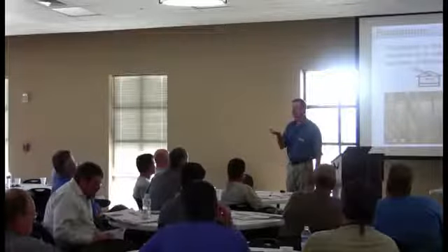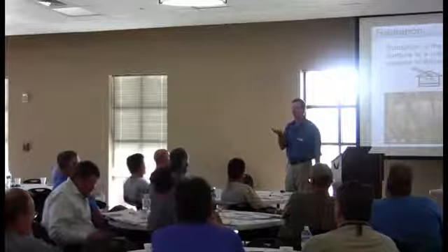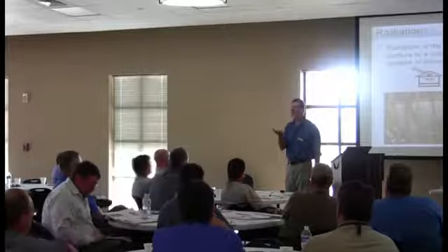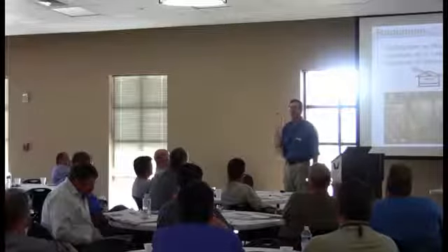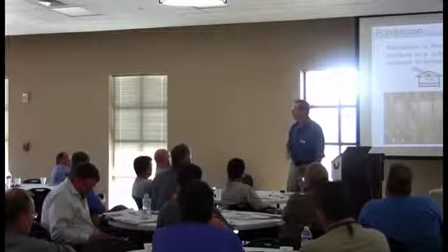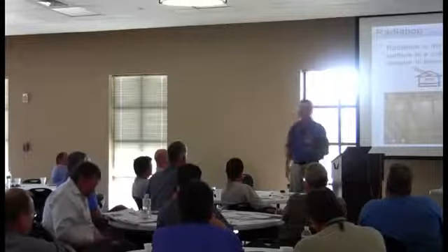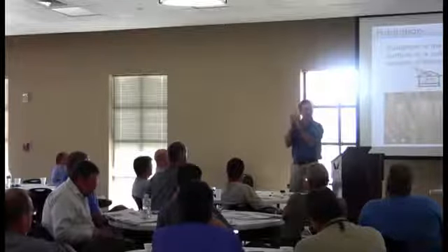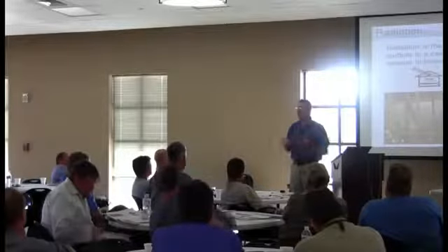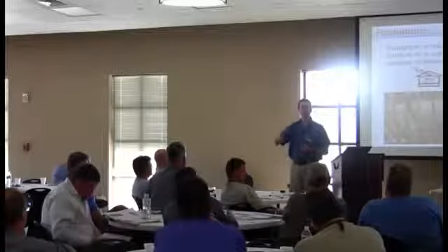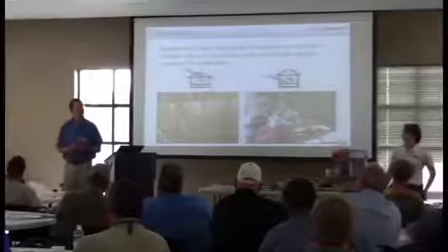Okay, Ed, you're in HVAC world. What does it mean if I tell you 8,000 BTUs an hour? That's over half a ton of air conditioning just from that one little window right there. So if that window is single pane, 80% gets through. If that window is double pane, 60% gets through. If that window is double pane with a low E coating, only about 30% goes through. So that's a pretty significant reduction from 8,000 BTUs an hour down to, in this case, let's say around 3,000 BTUs an hour. That's a big reduction.